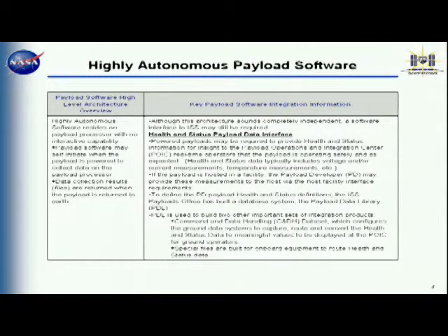PDL is used to build 2 very important products that make everything happen. The first is the command and data handling set, which is given over to the Huntsville Operations Support Center, and they develop telemetry and command databases in their architecture so that when you issue commands, they know about it, they can route it forward, and they can get your health and status data back from on board, process it, and make it available for monitoring to the real-time operators. Also, other additional files are built for the onboard avionics payload MDM, payload multiplexer, demultiplexer, that handles the routing of that health and status data.